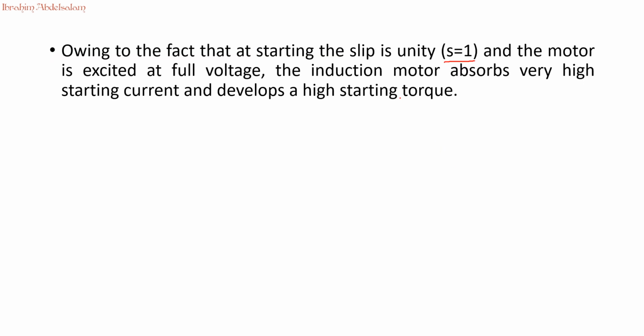So the problem is at starting, S is equal to 1. If we excite at full voltage, if the motor is connected directly to the three-phase bus bar at once, the motor will absorb a high starting current as we discussed before and develop high starting torque.